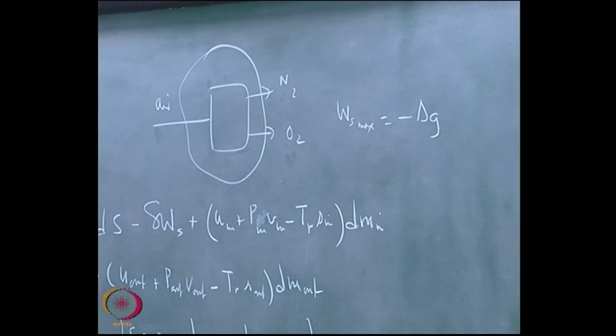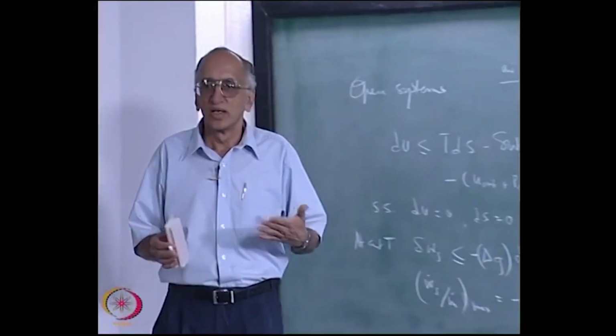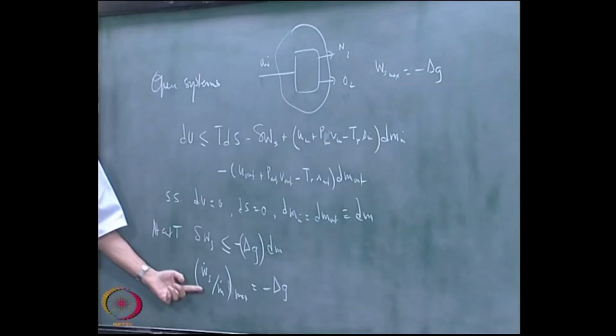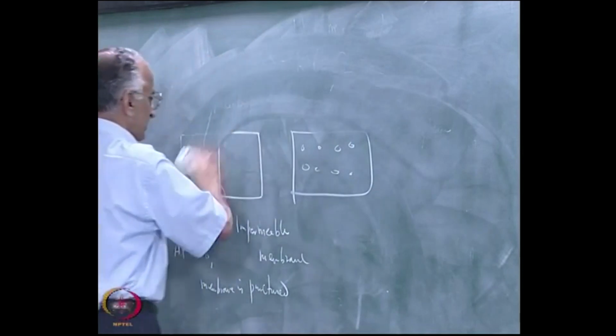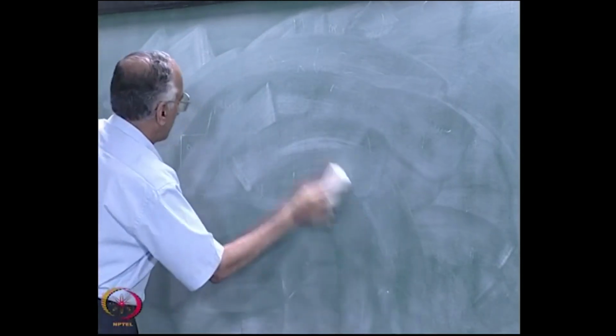Now I just want to point out here, you can tersely argue that even in non-isothermal systems it is delta G, and in isothermal reversible processes it will come out to delta H, but delta H can be derived, that Ws dot by m dot maximum in an adiabatic system is delta H, without any concept of reversibility. We will go ahead with calculations for various systems. The purpose of the entire course will be to calculate thermodynamic properties, the rest of it is practically downstream.